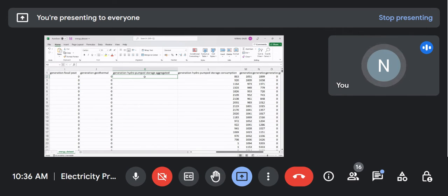So if you push the water from bottom to the top, isn't there a requirement of electricity for that purpose also? Sir, what happens is, you have 1,000 megawatt electricity available, but you require 900 only. So what do you do with the 100 extra surplus? At that point of time, they will run the pump. They will take the water from bottom to the top and consume that extra available electricity. Next time when there is a shortage, they will throw the water from the top and generate the electricity and supply it in the grid.